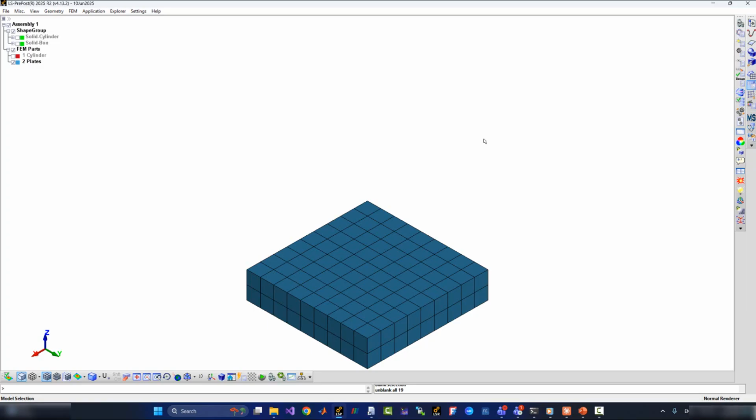Okay, now how do I create the copy of all these elements for the bottom plate so that I have another copy for the top plate? You go first of all to this button, the element tools, which involves all the edit commands, and find this button, the transform button.